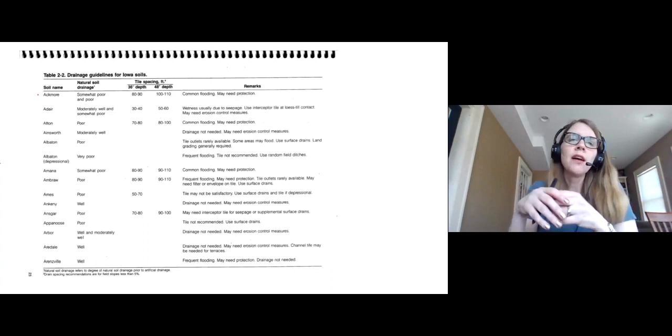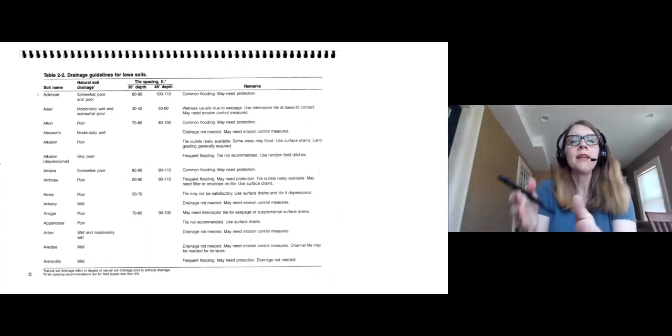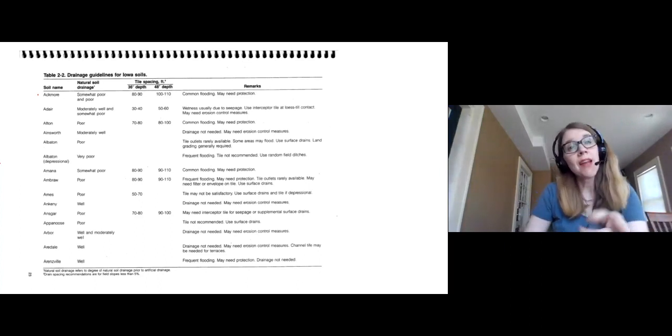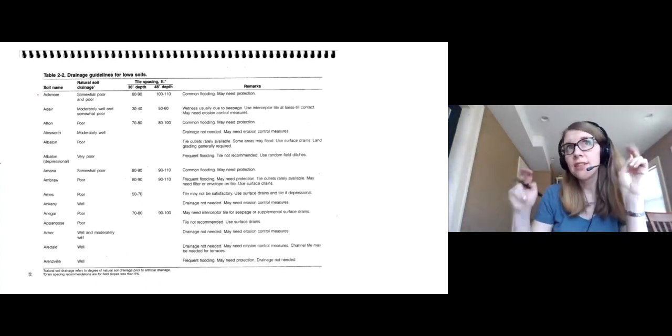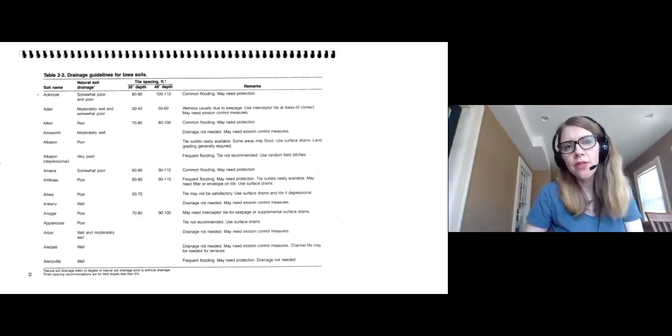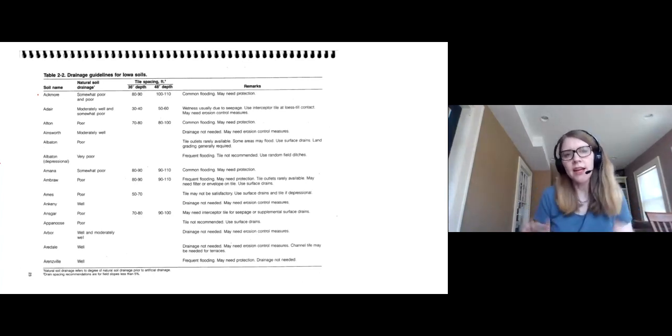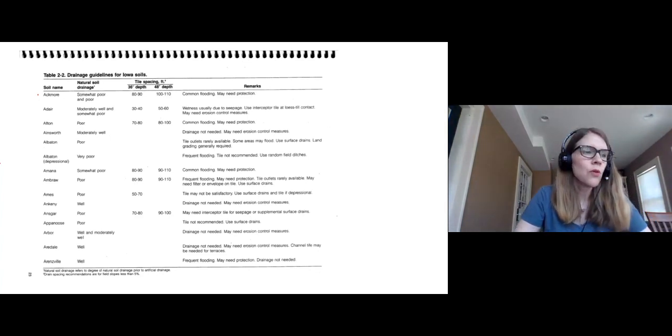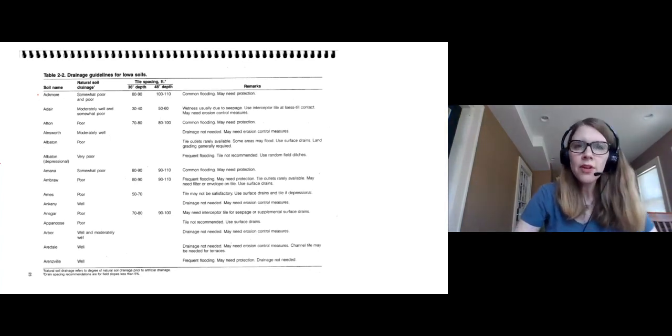And so if you're water quality minded, this would push you towards a shallower depth more than a deeper depth. And actually, shallow drainage as a concept is even shallower than that 36-inch depth. And then you've got to tighten the spacing up even more. Okay, so use local guidelines for depth and spacing.